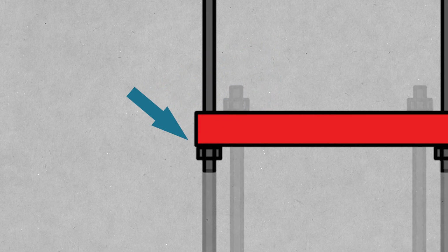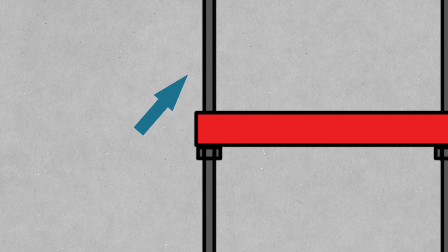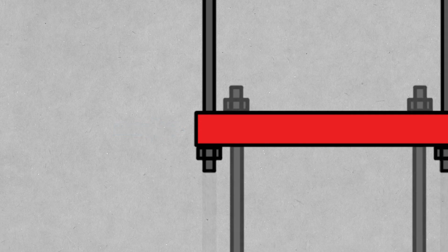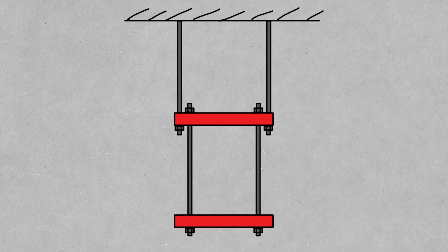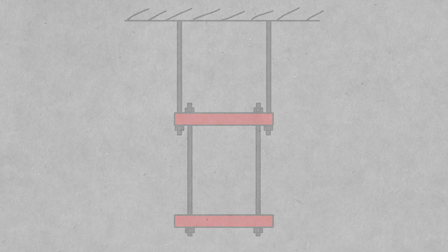If the rod had gone straight through as designed, then the rod would hold weight from both floors, but the beam would not. By changing the design, the strength of the bridge was effectively cut in half. This means that if too many people stood on it, it was bound to collapse. That's exactly what happened on July 17th in 1981.